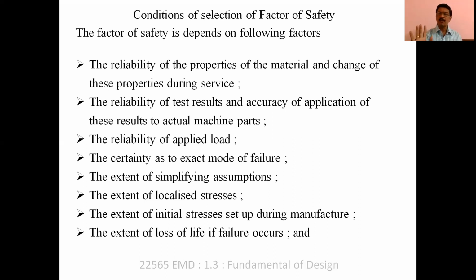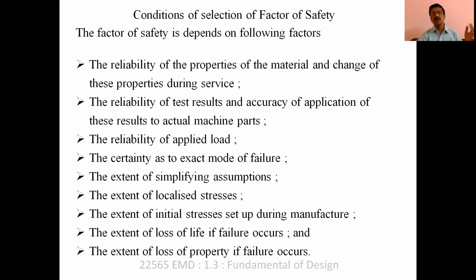Here, one thing is very clear. If I increase the factor of safety, the working stress or the safe stress value is going to reduce. It has a direct inverse relationship. If there is a loss of property, that is also directly related to our factor of safety. If there is a loss of property because of failure of a component, you should not take risk.